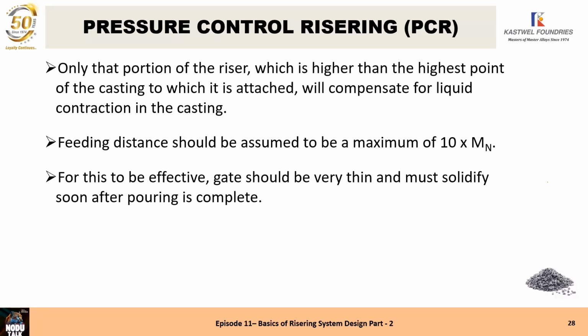So the riser can absorb the metal volume increase during the cooling of the metal in the mold and can give the metal to the casting when the solidification starts and the graphite expansion takes place. Then it can receive that metal and take all the pressure so that the mold wall is not expanded. So it gives the metal during cooling of the mold.